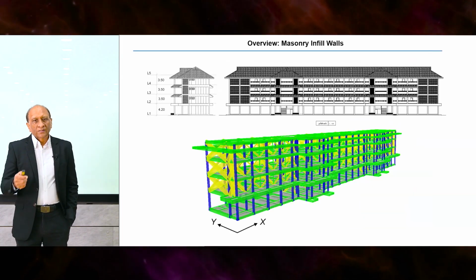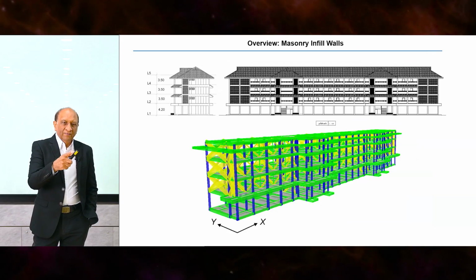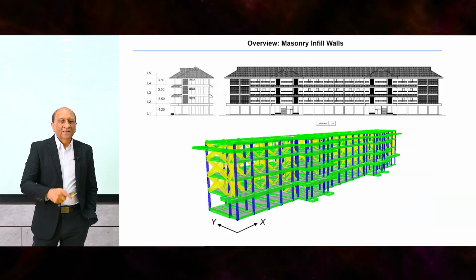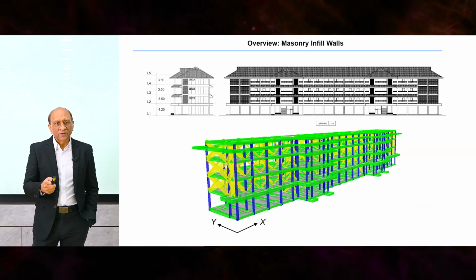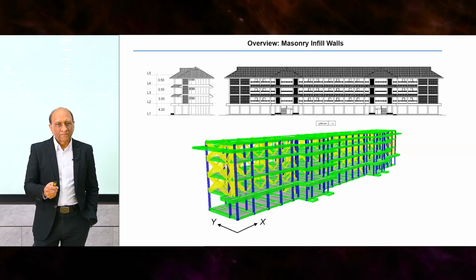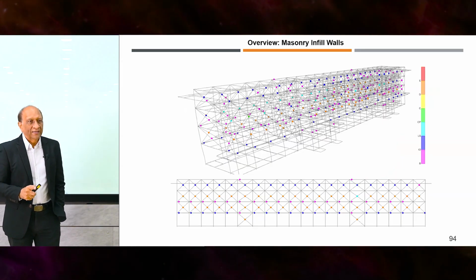So this is, for example, a small school building in the Philippines, where struts are used everywhere to represent the wall. Without that, this building's seismic response will not be reliable. And the good thing is that you can make these struts nonlinear.